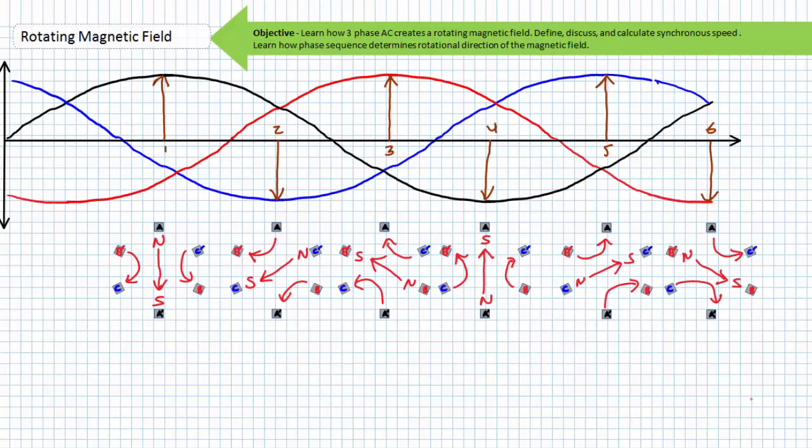Even neglecting overlap between adjacent poles, note what this physical and electrical offset is doing. It is dividing the complete stator into smaller portions through which the rotor can be dragged without experiencing unnecessary jerk or lull. The stator, in effect, has become a bucket brigade that smoothly ushers the rotor ever onwards in the clockwise direction. As one pole pair fades out, a fresh, angularly and electrically offset pole pair steps in.